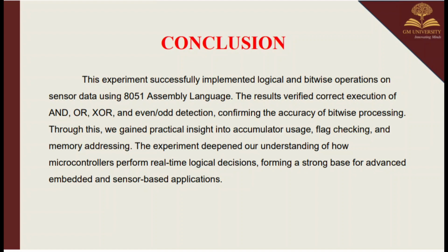This experiment successfully demonstrates how logical and bitwise operations like AND, OR, XOR and even-odd detection work on sensor data, and it helped us understand accumulator usage, flag checking and memory addressing, giving practical knowledge of how microcontrollers make real-time logical decisions. Overall, it built a strong foundation for advanced and sensor-based applications.